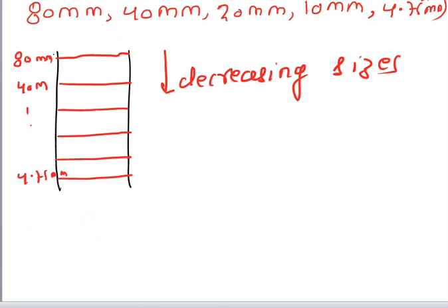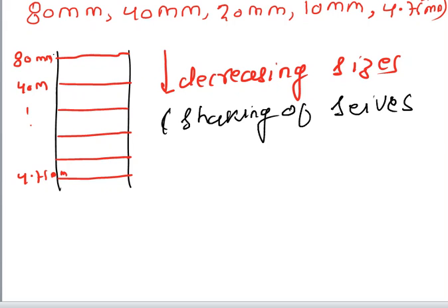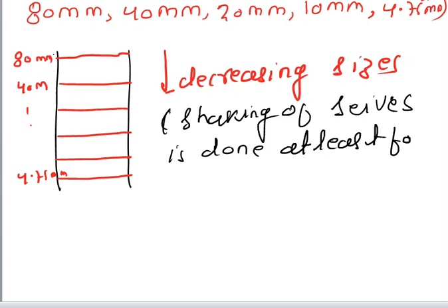It is recommended that shaking of sieves is done at least for 10 minutes. You have to shake these sieves at least for 10 minutes in order to get the correct result. And it can be done by two methods.